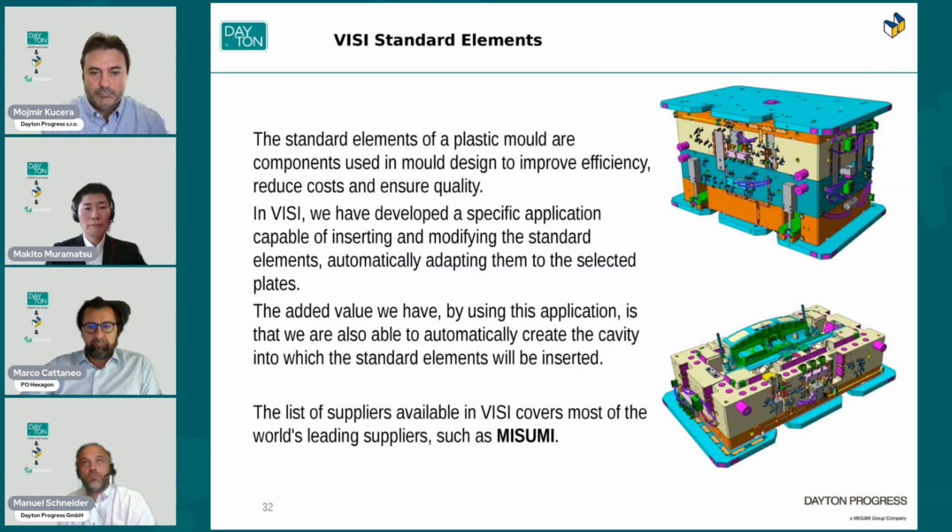Next slide, please. As we know, standard elements are a fundamental part of the mold design. This is why in VISI we have designed a specific application capable of inserting and modifying standard elements, automatically adapting them to the selected plates. The added value that we have using this application is that we are able to automatically create the cavity where the standard element will be inserted. The list of suppliers available in VISI includes most of the world's leading suppliers, such as MISUMI.